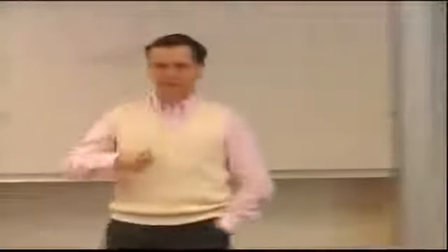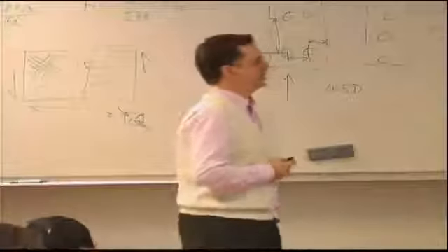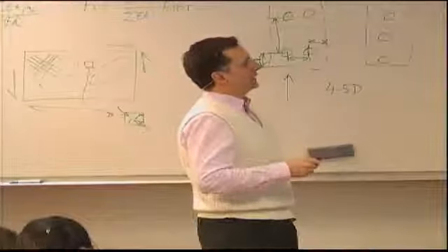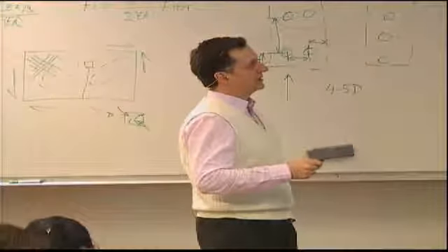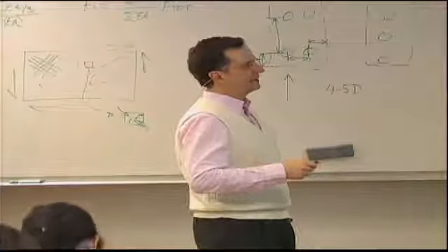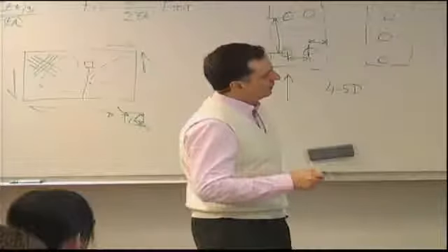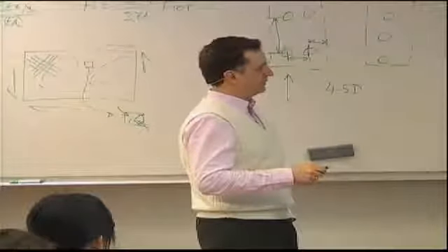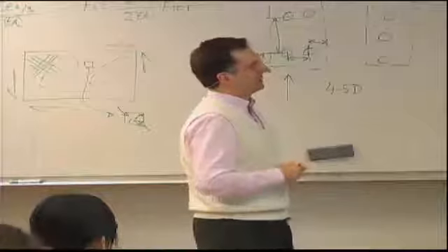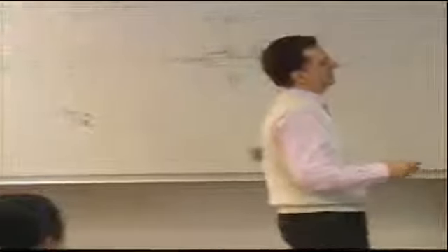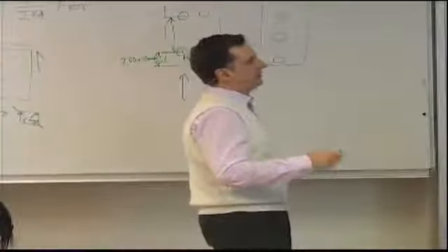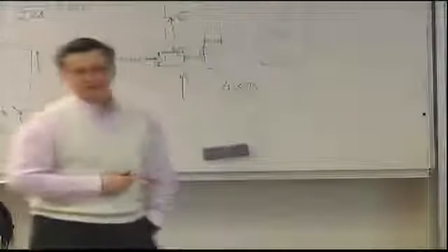So let's cover the concept of equivalent stiffness because it will be very useful from now on. I have a skin with a whole bunch of stiffeners. The spacing between the stiffeners is ds, and the panel width is BP. So the number of stiffeners is approximately the width divided by the spacing between the stiffeners.